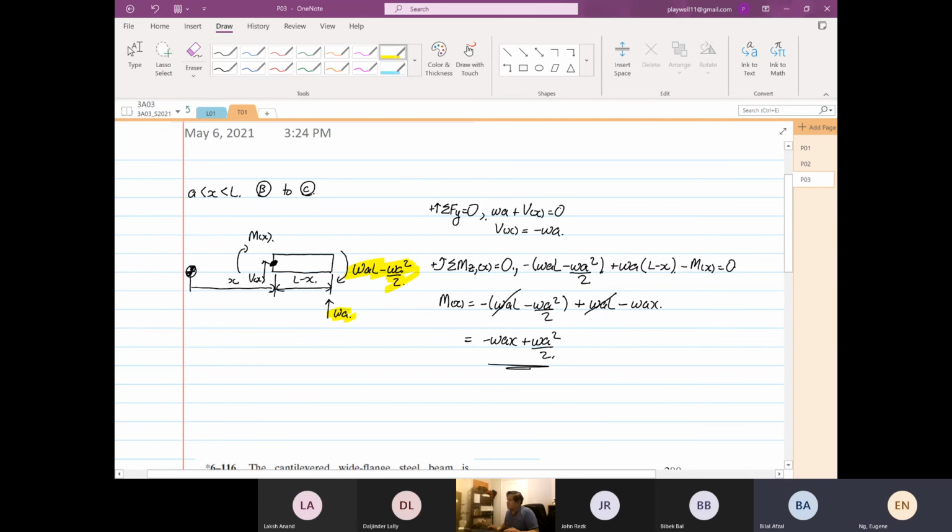Okay. Yes, and just a quick question. Is the bending moment the integral of shear force? It is. It is, right? Yeah, okay. It is. Okay, but I did not do that yet. This is a simpler method. You can also do that mathematically. You integrate your shear force equation, you get your bending moment equation.